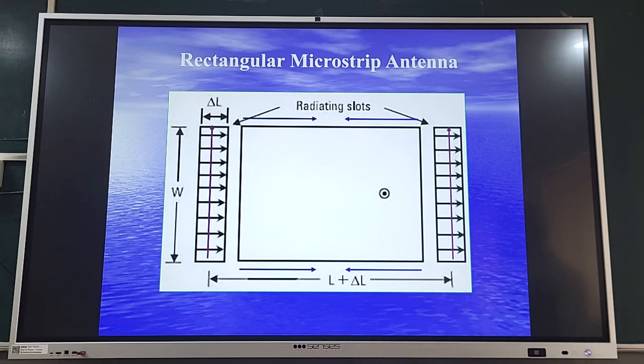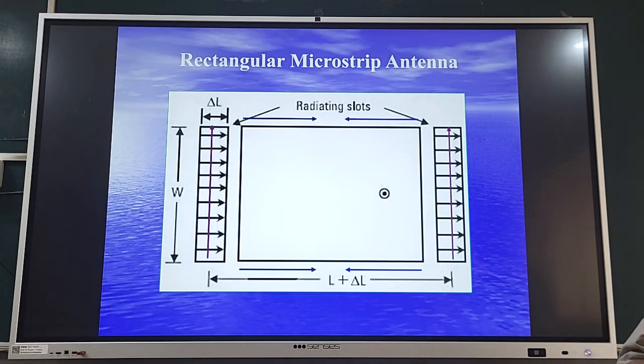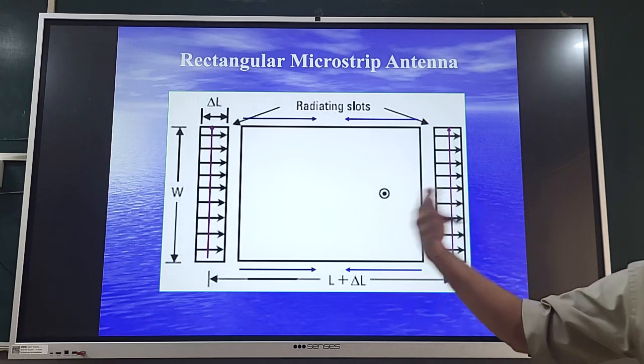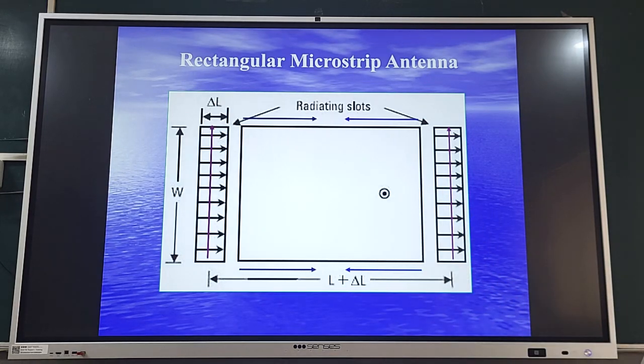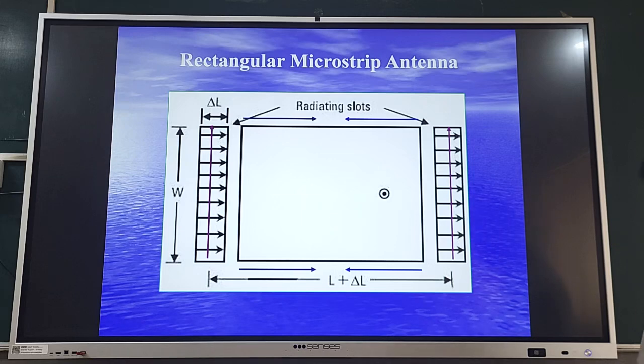Okay, because antenna measurements are to be done for the radiation pattern, for the polarization, for the VSWR or S11, as well as the gain. So there we will discuss in detail what exactly and how to identify the E and H plane specifically for random or irregular geometries. Because later on, when we go to circular patch and equilateral triangular patch, they are all regular geometries. For regular geometries, identification of the plane is very simple. Against that, for irregular shape geometries, because in your projects also you may be asked to do some irregular geometries, how to find out?